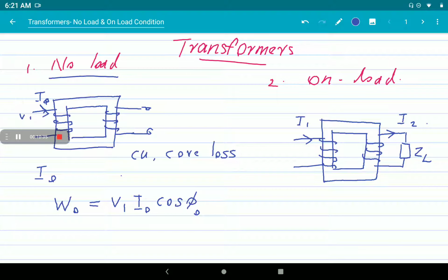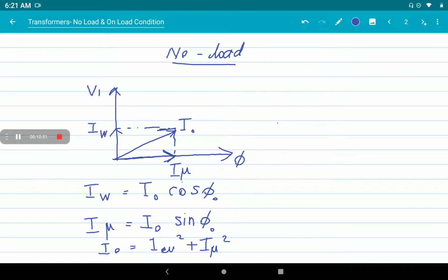But on open circuit condition there is no load on this side, so there is no current in the secondary. Only a small current to magnetize the core is there, so the I2R loss is less. So we can consider that the copper loss is negligible, and the no load primary input is practically equal to the iron loss in the transformer.